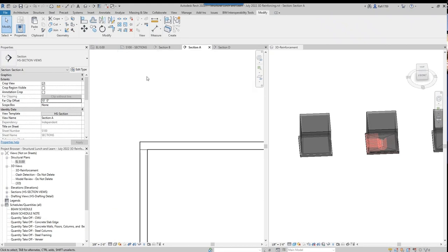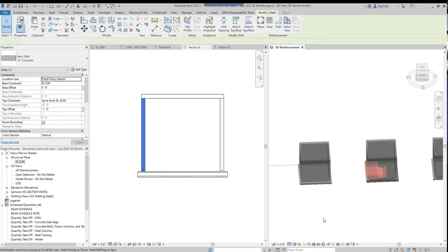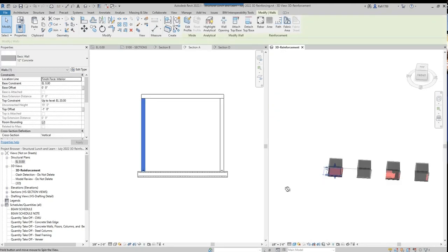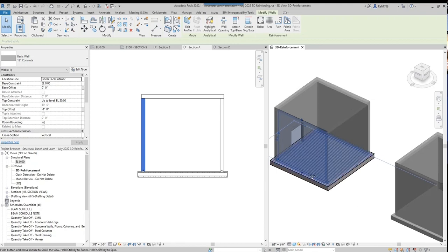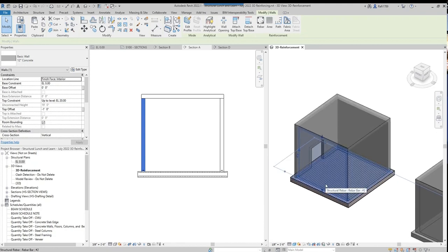just to keep it simple. Okay, so when I'm doing my wall reinforcing, I'm looking in 3D to see what I have in my wall. Before I even put any rebar in, I'm going to see, do I have any openings? Is it stepping? How many sections do I have? Is it just one? Is it two? Is it three throughout this particular wall?